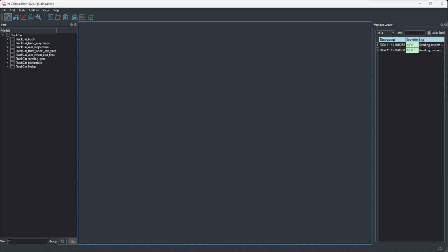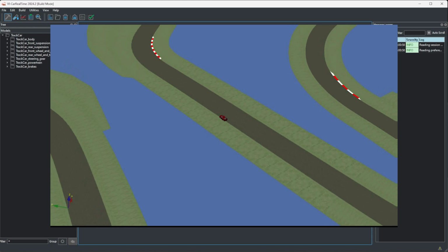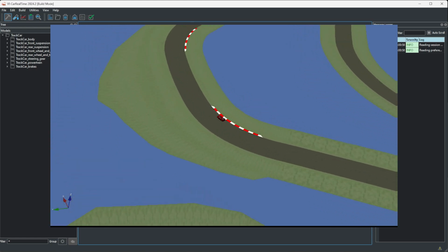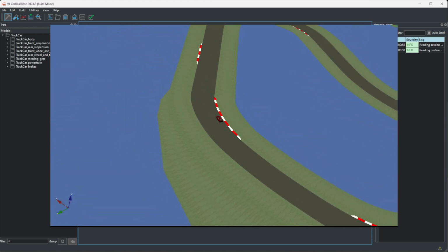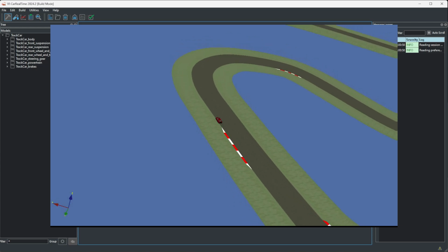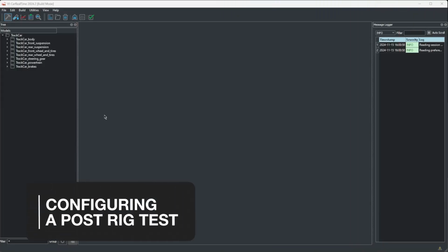Since we're using a heave sweep in a wide range of different frequencies, we are creating a generic base setup for the car that should perform well in many different tracks. When tuning for a specific track though, we could focus only on the frequencies that would be more relevant to it. Let's start by setting up the test that we will use to investigate the heave frequency sweep.